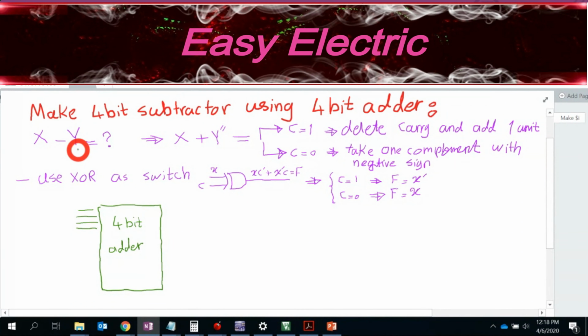If I give you a binary number, how could you get the first complement of that? Yeah, definitely it is a NOT. That's right. So the second input should be just NOT. Why? Because whenever you want to find the first complement, you change 0 to 1, 1 to 0. What it means is you just NOT the second number. So I use 4 NOTs here.